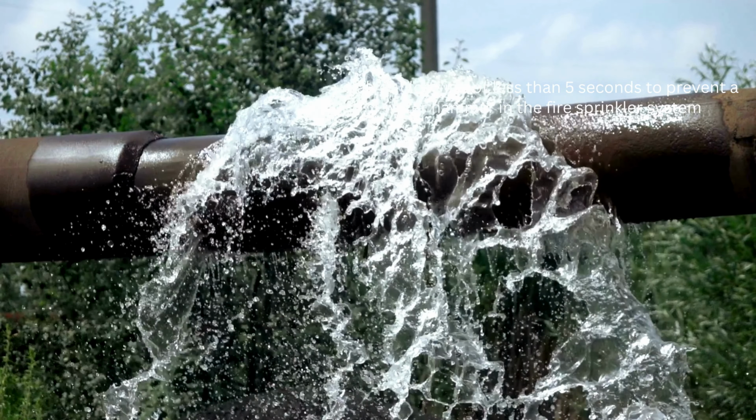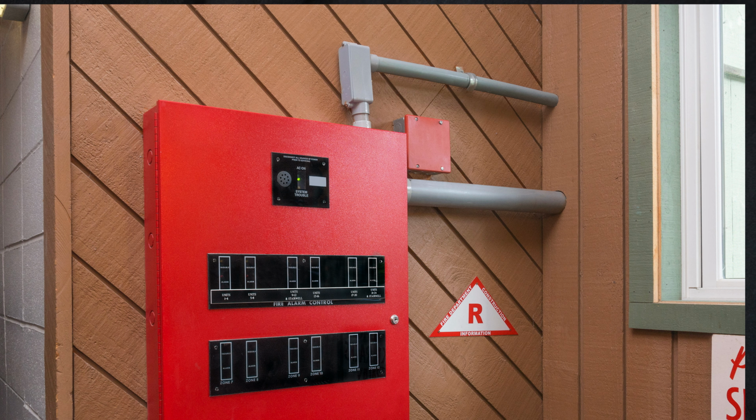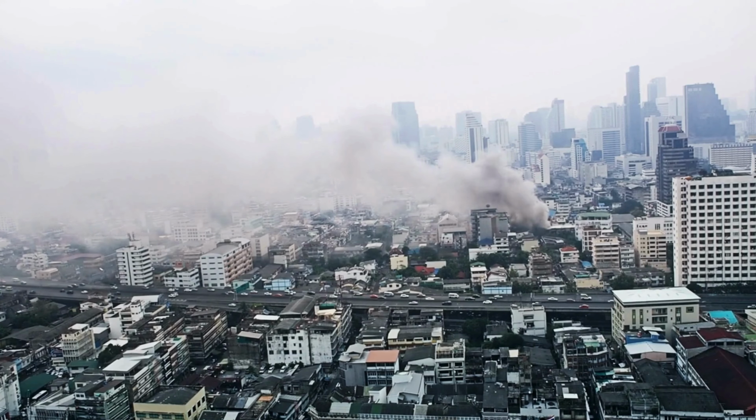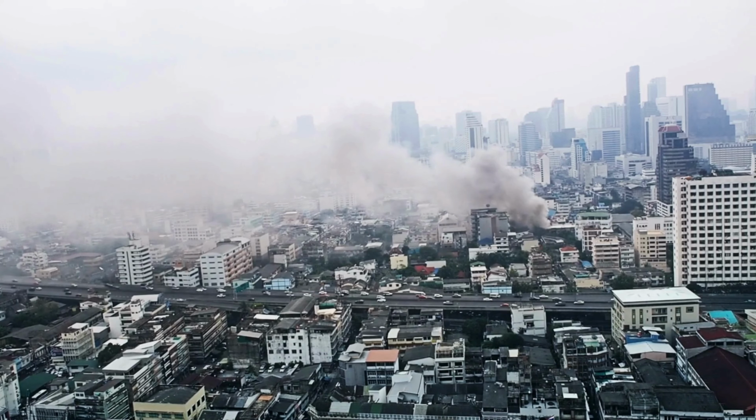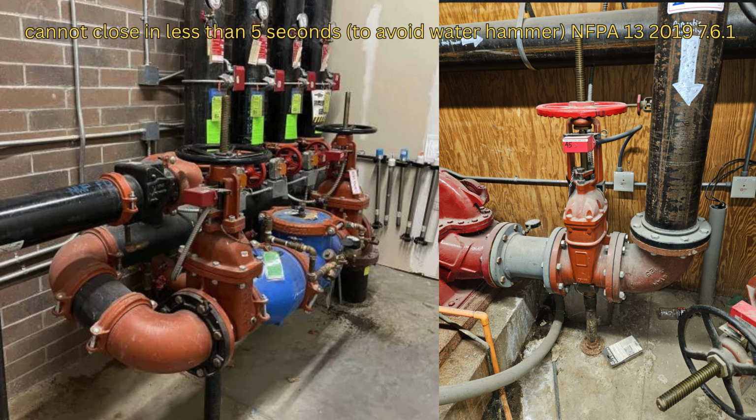Every valve that has an impact on an active system shall have a form of tamper switch on it, notifying the fire panel if the valve is being tampered with. This is very important. According to NFPA, automatic sprinkler systems have a 96% success rate, with over 80% of the failures due to a closed valve. This prevents that.